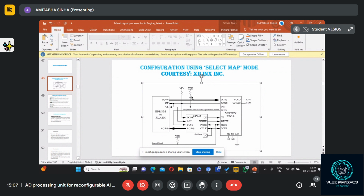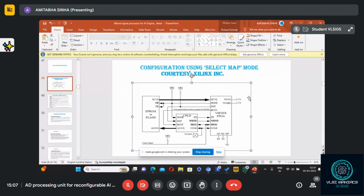Yes, sir. So this is D0 to D7, meaning 8-bit data lines. Through this data bus, the data will be delivered from flash memory and downloaded to the FPGA one by one. So that is the bit stream.